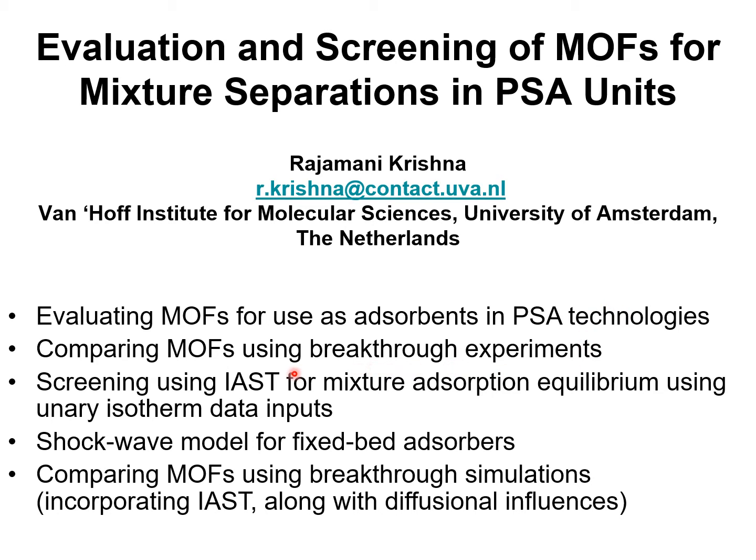The MOFs can be compared by using breakthrough experiments on a laboratory scale. Screening and comparison of MOFs can also be carried out by using the Ideal Adsorbed Solution theory for mixture adsorption equilibrium. This theory uses the unary isotherm data as inputs.